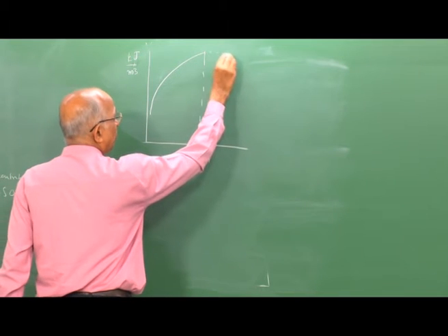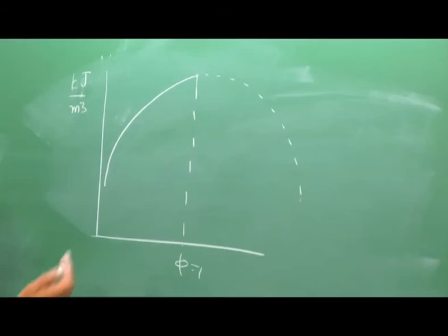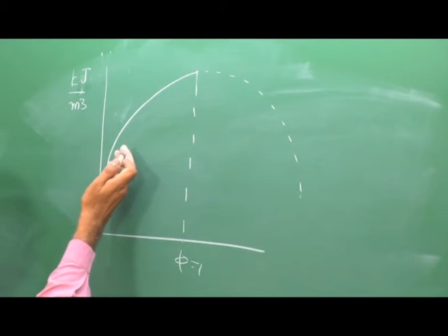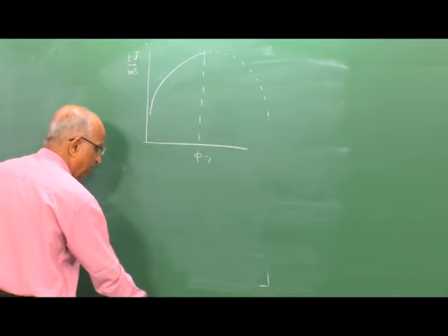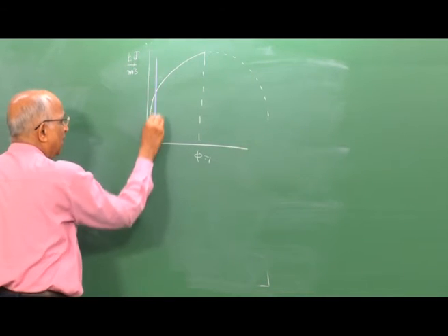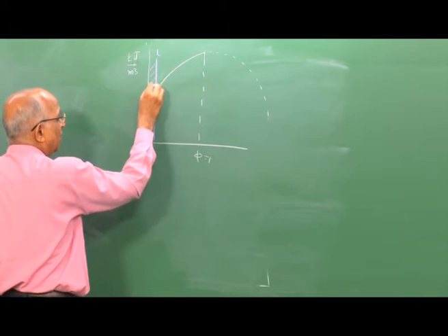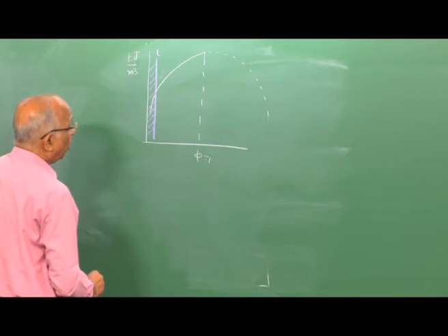It also drops off in the fuel rich region, but I am not interested in the fuel rich region, because it does not correspond to accidents involving spills; in most spills you form lean types of mixtures. Let us say that the lean limit of mixture corresponds to this L. Below this it does not really burn, because the heat generated is so small.